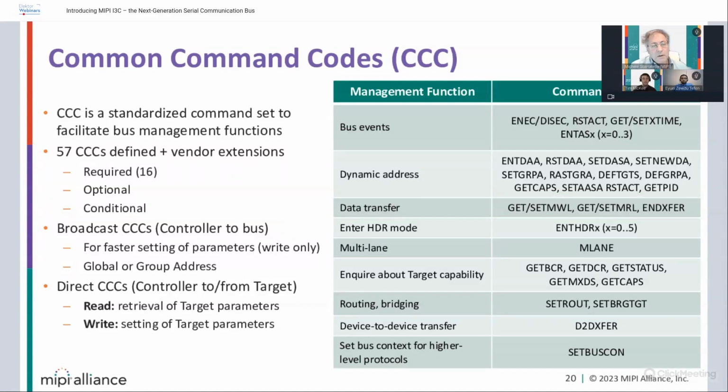We have a slide after to explain this a little more. Basically, in I3C, you are not hardwired with the manufacturer address as in I2C. In I2C, you buy a device, and the device has a fixed address, or maybe has one or two pins to manage it, but it's basically hardwired. Here, it's dynamically assigned by the controller.